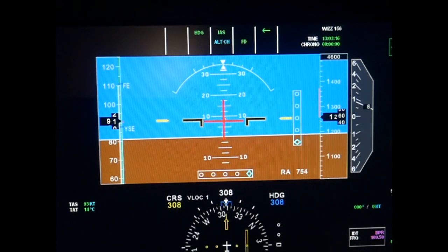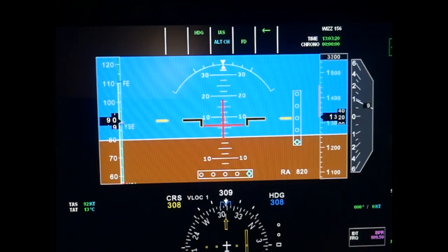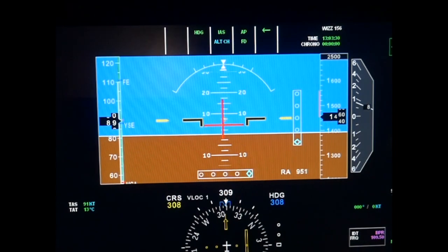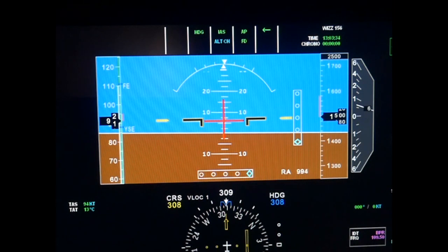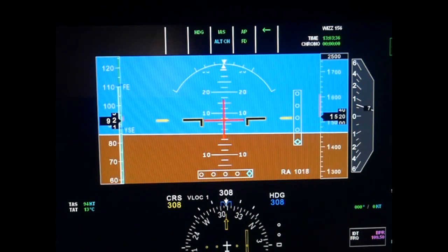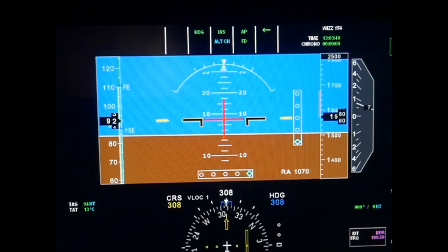ATC tells to stop climbing at 2500 feet. New altitude should be set by the altitude selector knob. 1000 feet before the selected altitude, the altitude alerter provides oral alert. Pilot should call 1000 to go, regardless of the altitude alerter.